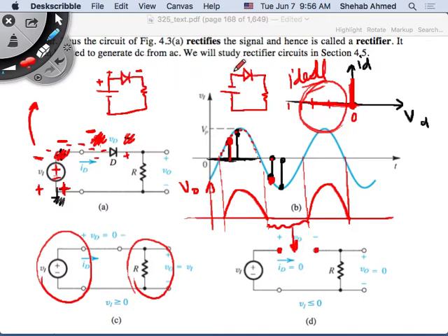Here, this is the most negative value in the circuit, which means that on the other side, it's going to be more positive. So it will block. So you can do it that way, this way, whichever way. This is an application of the diode, right? And it's a non-linear operation of the diode, right? It's either on or off, right?